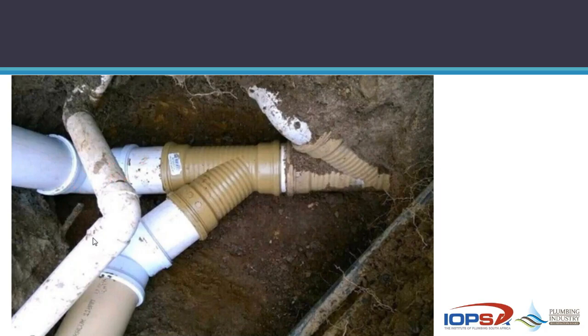And then this waste pipe disappears under the ground from the house and it ends up going around and ends up going into a reducer in that 45 bend there. So couldn't clear the blockage, opened the whole thing up, replaced with this material here, left side blockage occurred again, next plumber comes along, and this is what you're stuck with.